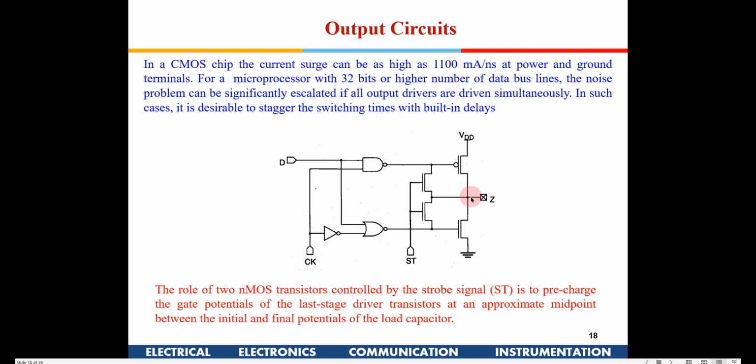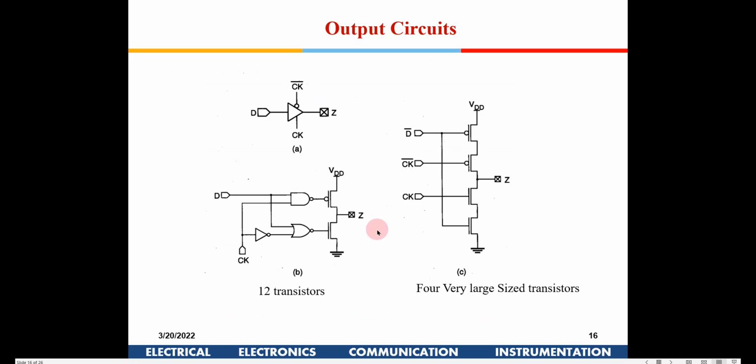Aman, what it does is just before driving the circuit, okay. So what does this circuit do? Let me go back here. What does this circuit do? When the clock is 0 here, I have a 0 here, right? And when it is 0 here, it will be 1 out here. So this will be switched off. Similarly, if it is 0 out here, it will be 1 here. This will also be switched off. This will be in a high impedance state, the output pin, right?